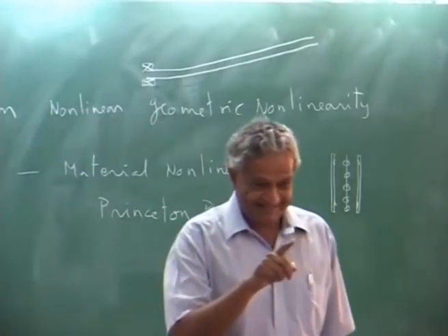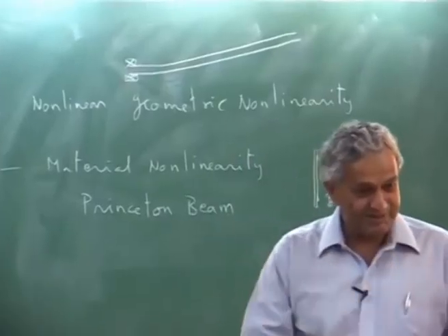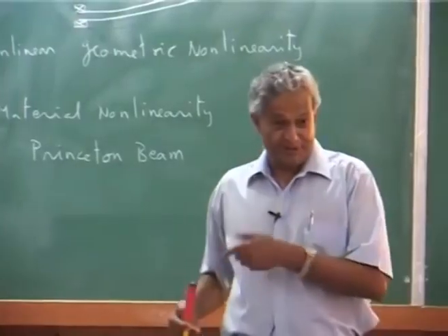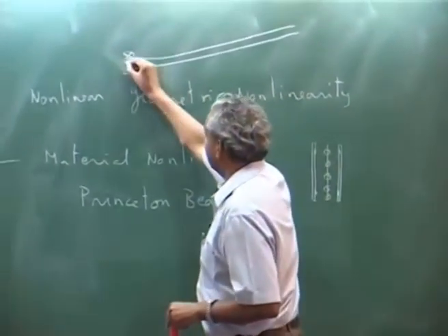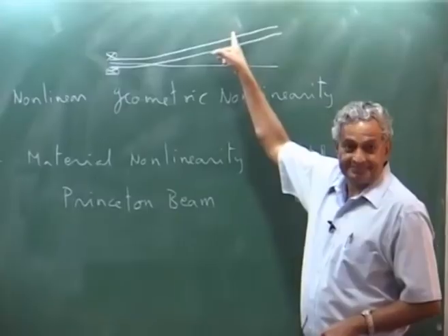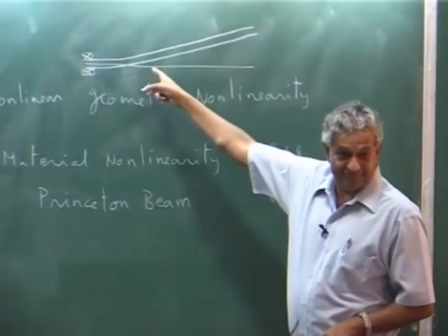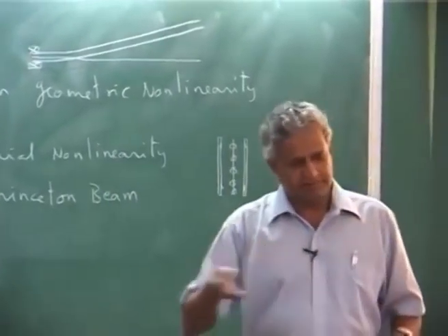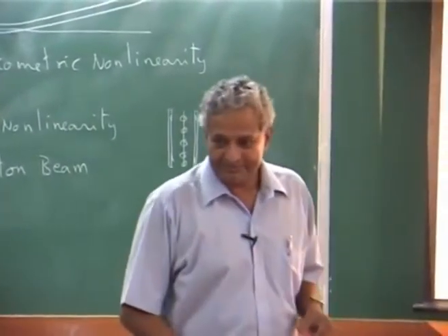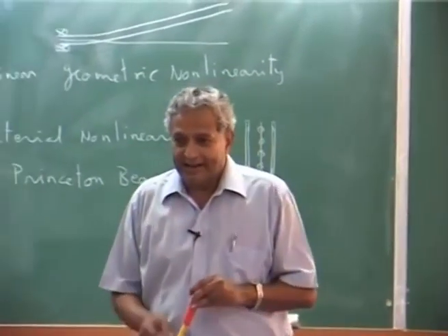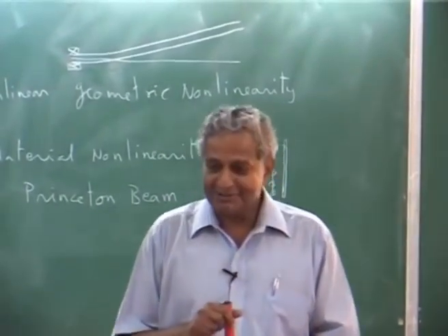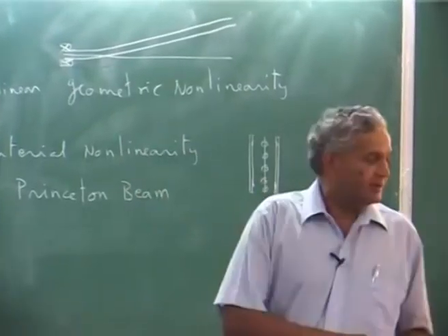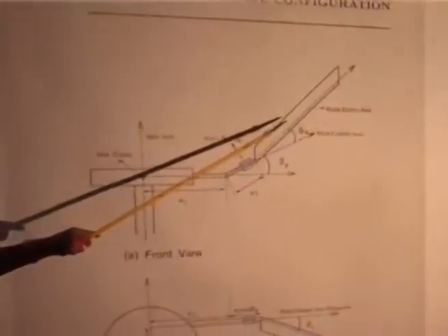Composite blades, that is why composite blades are easy to manufacture with that shape. Pre-droop, this is the droop, because you see, metallic blade is tough, but composite blades are easy. The ALH blade is a composite blade, so it is there, okay. Advantage, that I can only say in words. See, one is whether it is a pre-cone or a pre-droop.